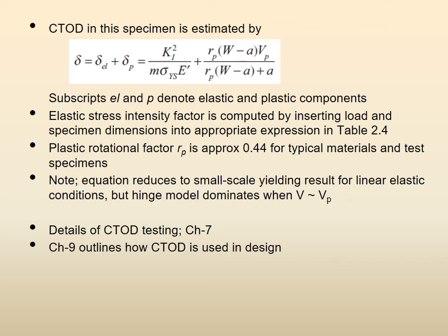Remember, the yield point is defined at 0.2 percent offset, which means actually 0.002 and so on, right? So it is very small compared to, even if you go to 0.1 strain in the plastic region, where 0.002 is a very small fraction. So the same thing here: the V, the crack tip opening, because of the elastic region is very small and the V plastic is much bigger.